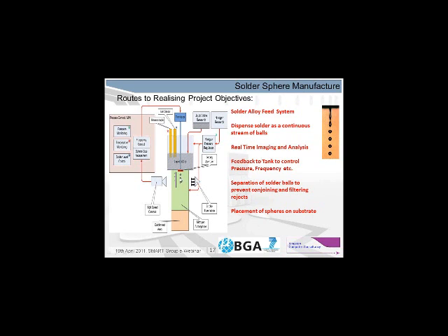The ball size, shape, consistency, and numbers will be analysed using very innovative FPGA hardware-based assessment. This will be compared to the CPK that we're requiring to achieve, and a feedback loop will be sent to the production system.